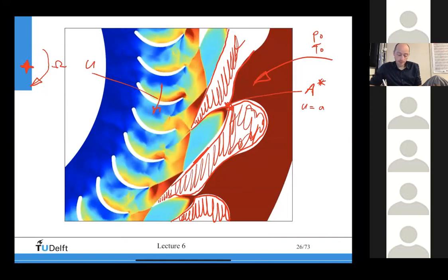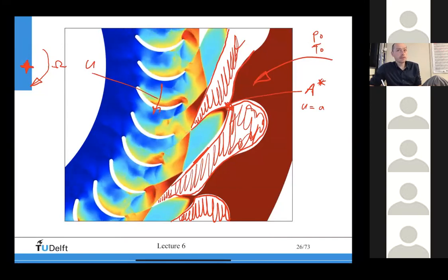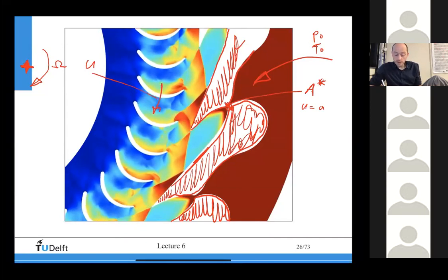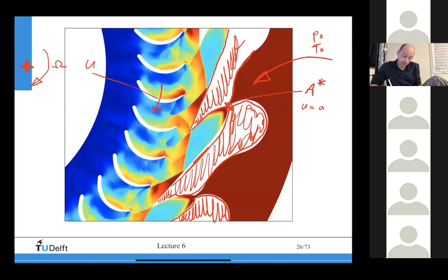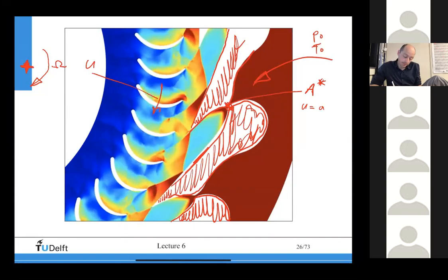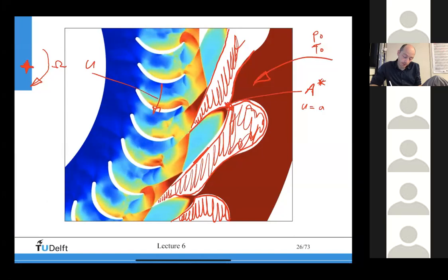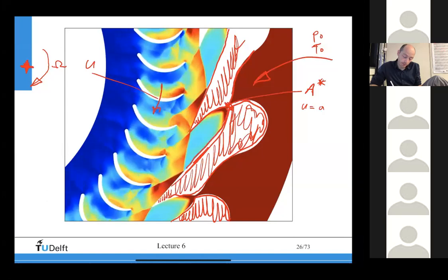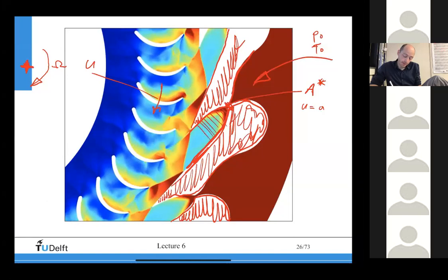And from gas dynamics or thermodynamics, we know that if we want to further accelerate the flow, we now need to have, instead of contraction, an expansion here, right? First I have a contraction, I have a nozzle, and then I have a diffuser here. See the diffuser. The cross-sectional area increases, right?